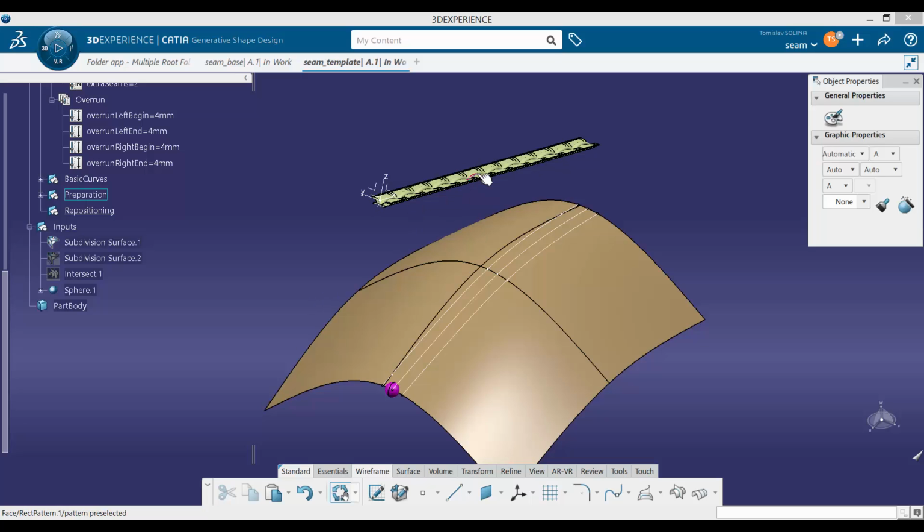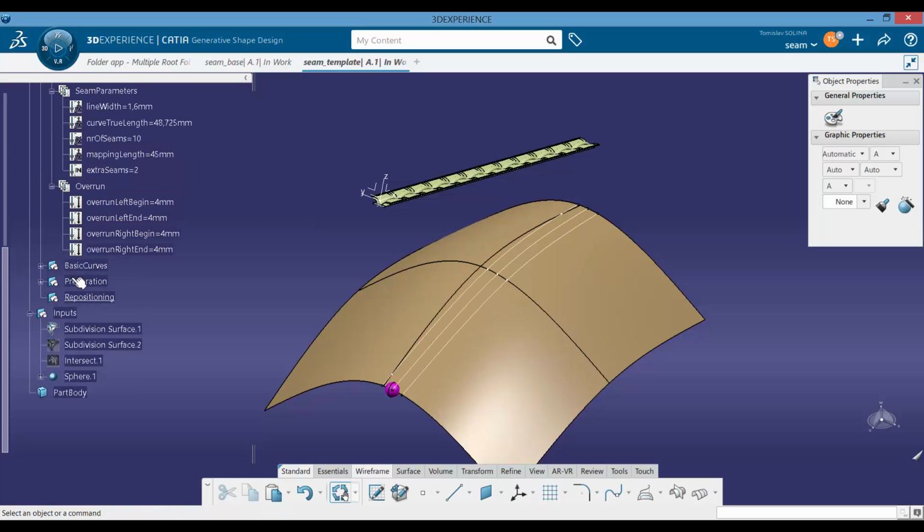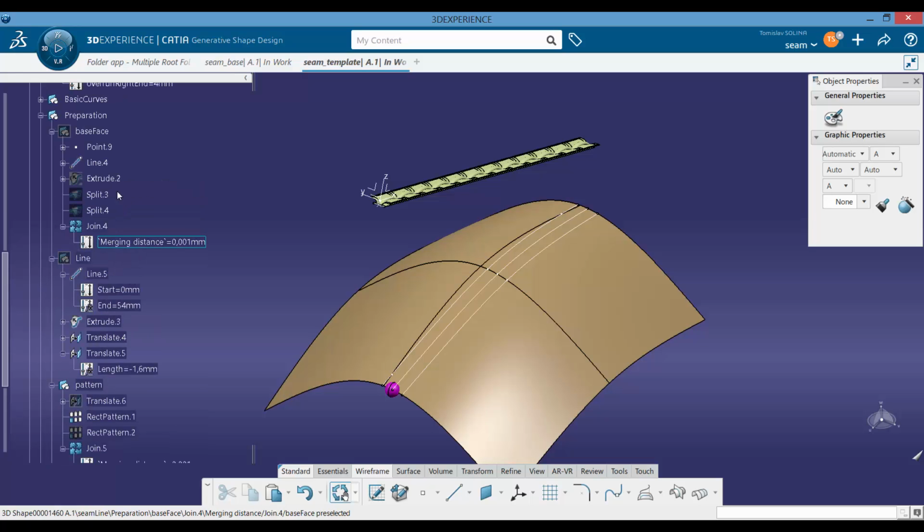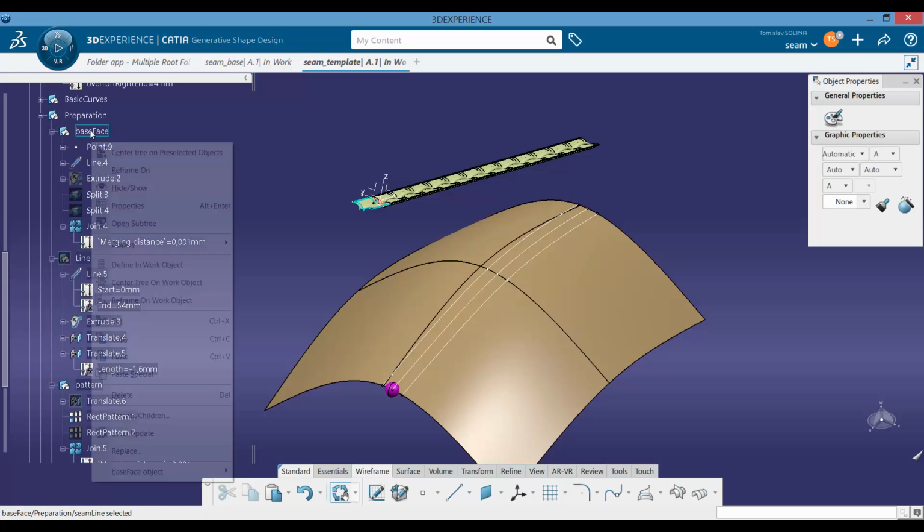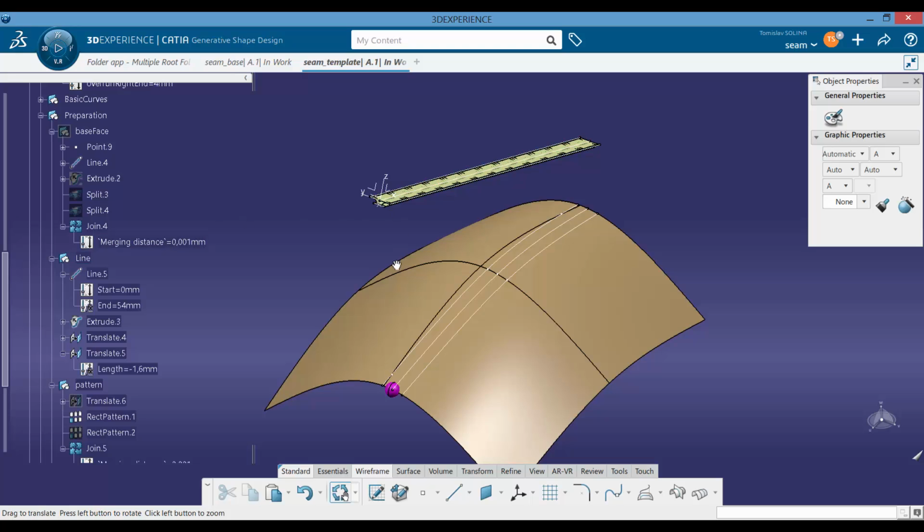First we'll put axis system here in the middle, then we'll put axis system there in the middle. Why in the middle? Because then when we are doing wrapping of those surfaces, then chance to do mistake by calculation is lower. In order to do it on the upper one, we have our preparation set where we started creating those base elements. Where was the line?